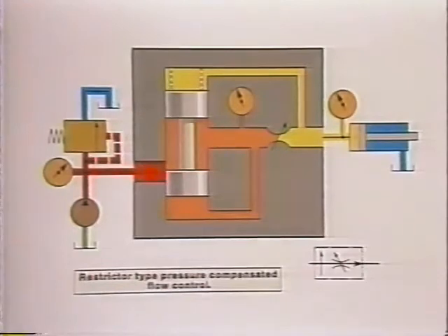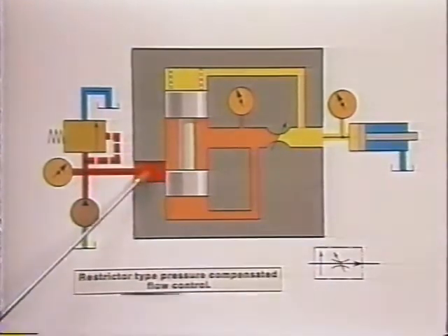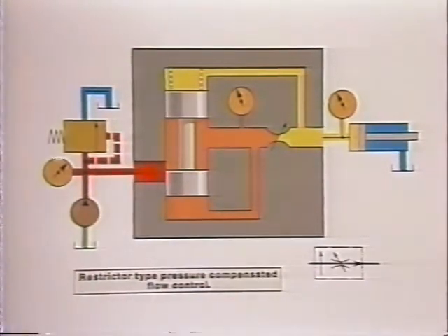As it moves up, the opening gets smaller, and as it gets smaller, it restricts the flow rate entering the valve to what 20 psi can push through the throttle. In our case, 5 gallons per minute. The excess flow again must return to tank over the relief valve.